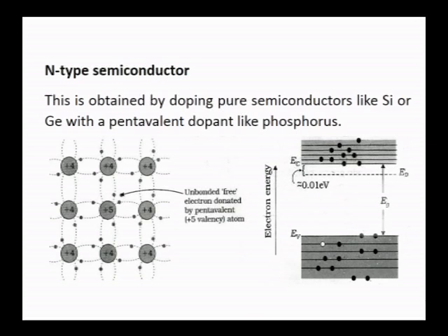And in this particular picture you can see that one such impurity atom is added to the crystal structure of a germanium or silicon for that matter. See, this being pentavalent, an additional electron is there along with the 4 electrons which take part in the bonding process. That way we can say that a pentavalent impurity added to the crystal structure contributes or donates one free electron to the crystal structure. So if we have added some 100 such phosphorus atoms, 100 free electrons are available.